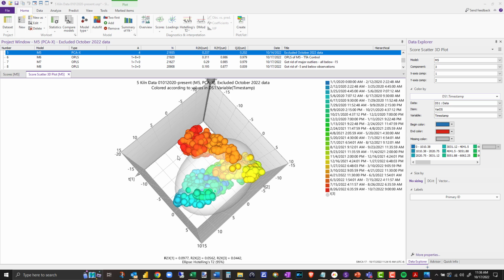There's going to be little deviations plus or minus. So why don't we just go to 10 collections every hour? That'd be every 6 minutes. We just pull data out, and if something starts a little off or a little early, we will at least be shifting a little bit around it. Or split the difference and go to 5 every 5 minutes, 12 observations an hour. So we just reduced your data, but didn't really reduce the actual variation in your process by a whole heck of a lot.